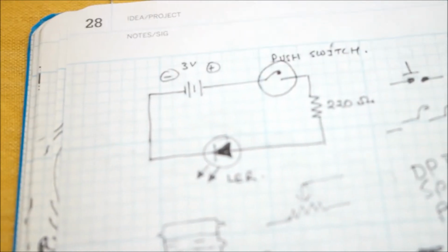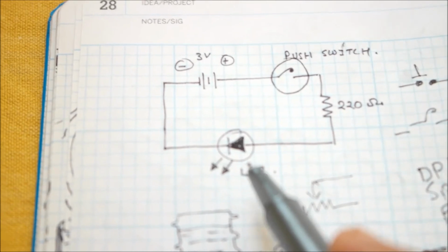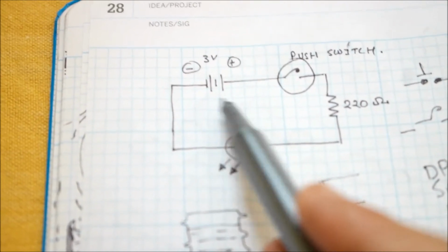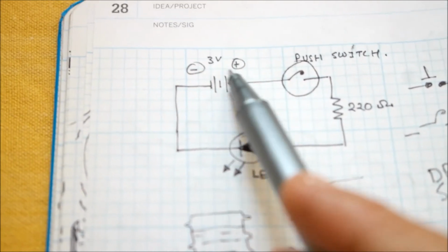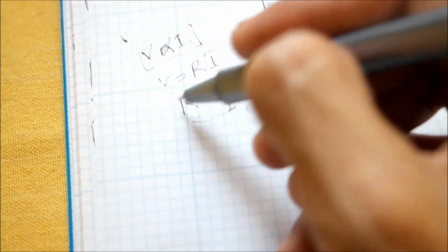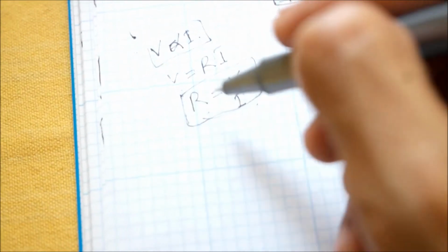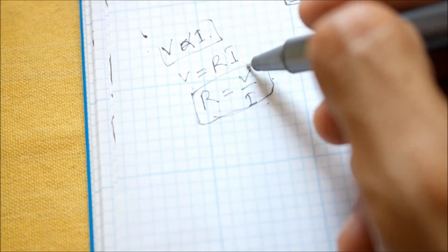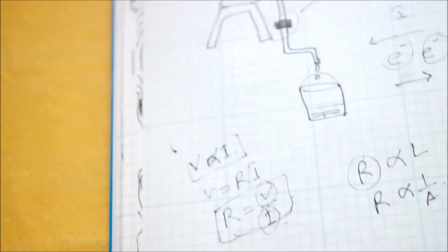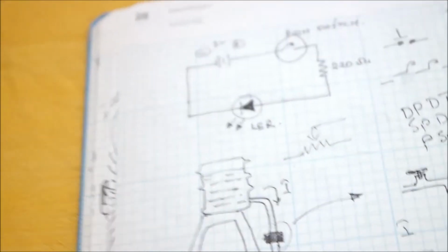So in a circuit, if you know how much current is needed for an LED at maximum, or how much current this battery can provide, and you know the voltage of the battery also, you can easily calculate how much resistance you need for the circuit, because according to this equation, for finding the resistance of a perfect circuit, you need just voltage and current. So that's how you actually use this concept to find resistor values for specific circuits.